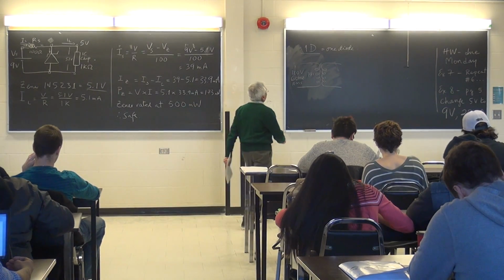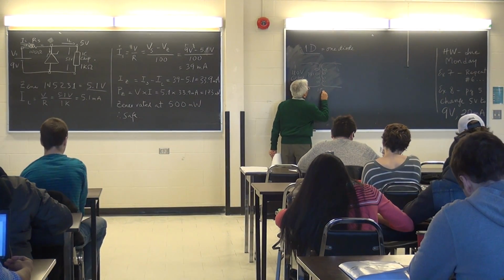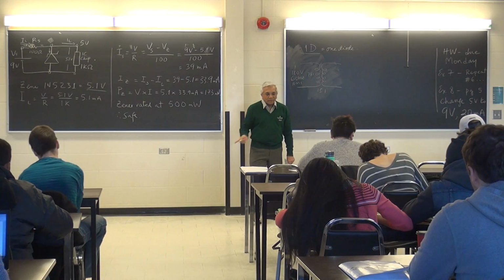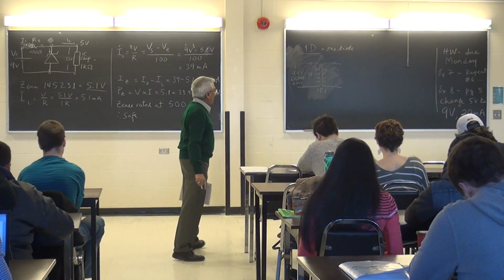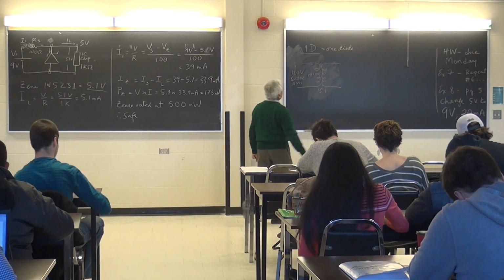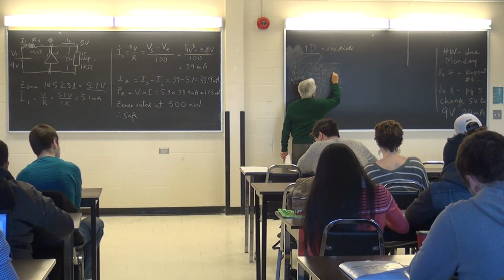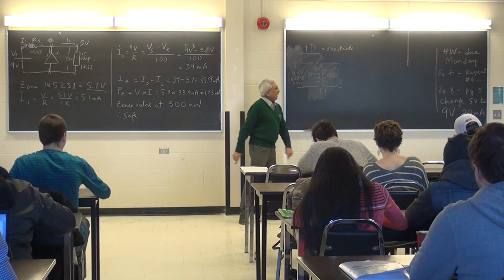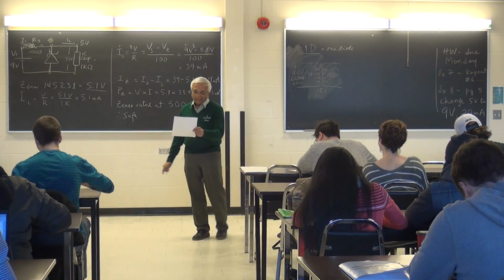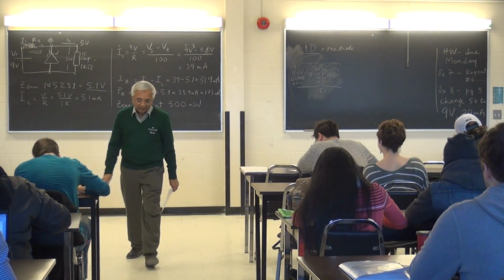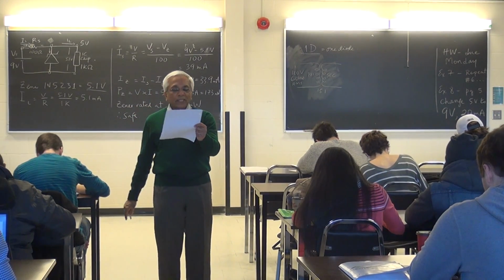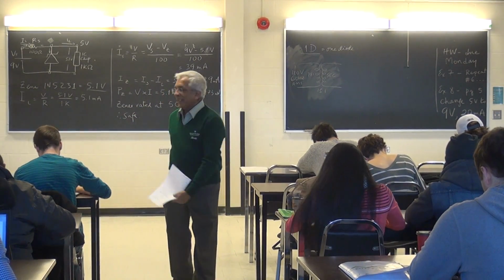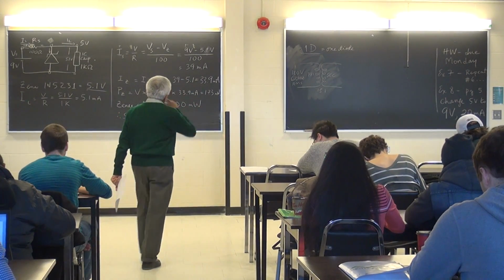So I write down 15:1 here. So it's by that ratio that I reduce the voltage on the secondary side. So I label the other side secondary, and I calculate the secondary voltage. So let's do that calculation first. So the first calculation at the bottom, item A, is V secondary RMS.